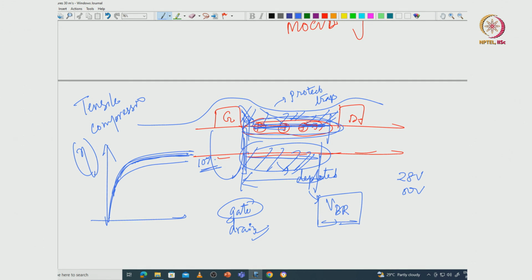your devices, okay. And once you have the silicon nitride recipe, you can again put field plate on top of that, for instance. You can have a gate first process, you can have a gate second process, etc., but those are the later stage. But what is more important now to understand is that your current can collapse under pulsing, large signal pulsing, and we need to fix this current collapse in order to be able to get meaningful power out of a gallium nitride RF device, okay. And silicon nitride passivation is the key to enabling that, okay.